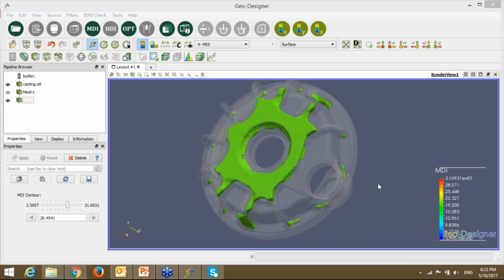The basic principle in the casting part is, if you do not have an external cooling effect, that means you don't have external cooling in terms of chill, or external cooling in terms of a cooling channel like you have in high pressure die casting or low pressure die casting, then whichever region has the higher mass will solidify last, and that is the region which is likely to get hotspot and shrinkage. This is the basic concept when we speak about sand casting and investment casting process.